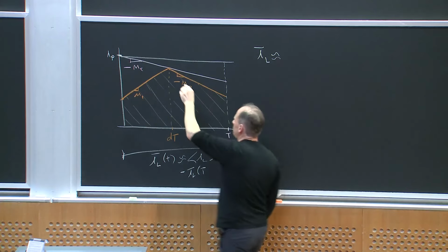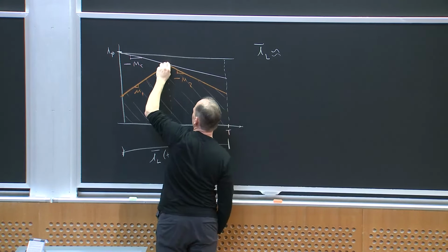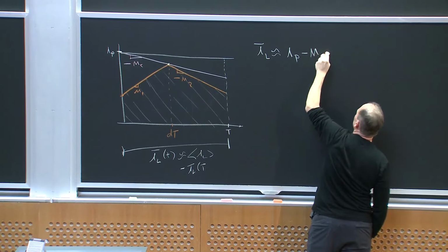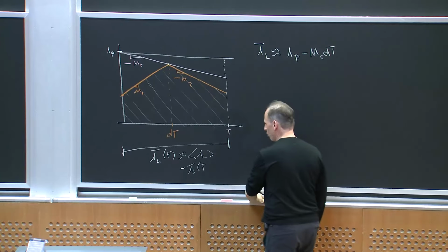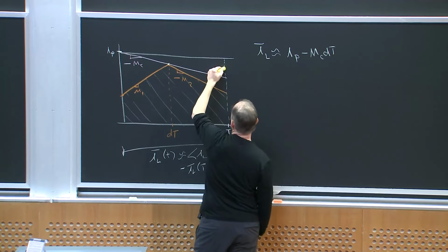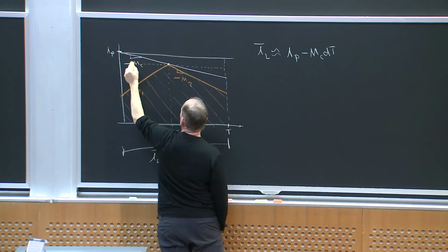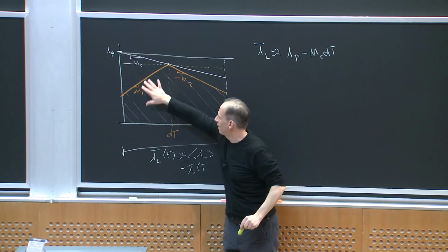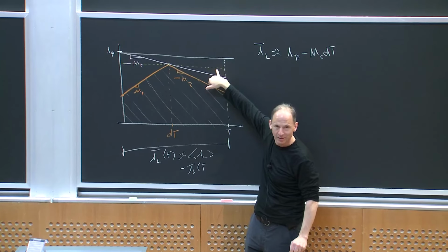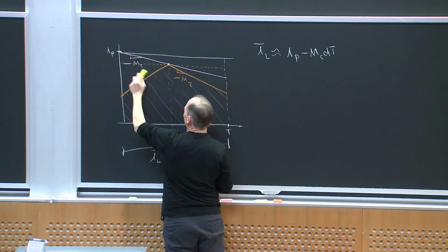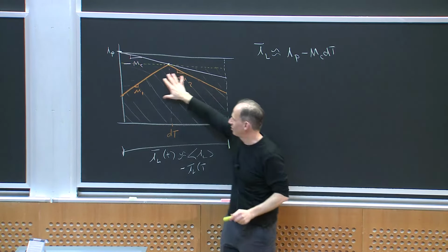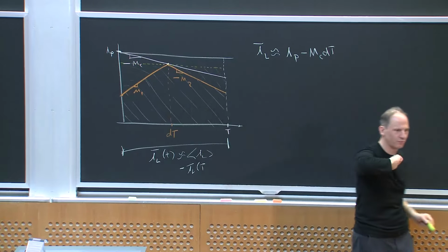Okay, well, let's see. The peak of this waveform here is I peak minus MC dt, right? If I just use this value, that would be basically if the orange waveform looked like this green waveform, that would be exactly the local average in the cycle, right? But what I really need to do is subtract off the average of this area and the average of this area, right? And then I'll have the average underneath the inductor current curve, right?